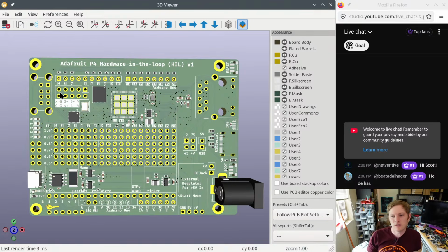The thing I was mainly considering where that might not be true is how you load the Python code that you're going to run. For every test run you're loading CircuitPython, and then you're going to load multiple images of the CIRCUITPY drive, and that's a lot of flash erase time and test time. So I was briefly thinking about ways of storing it in a RAM that's acting like a flash, so that you're not actually paying the flash cost. But then your hardware is not truly what the hardware is, and these boards are pretty cheap, so optimizing for flash wear is not actually that important.